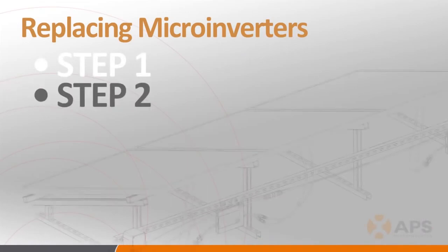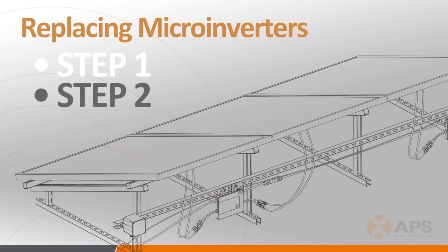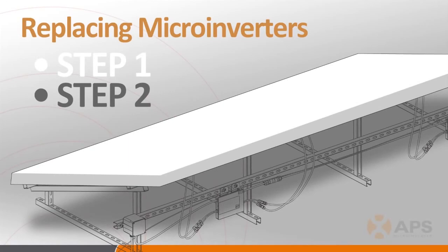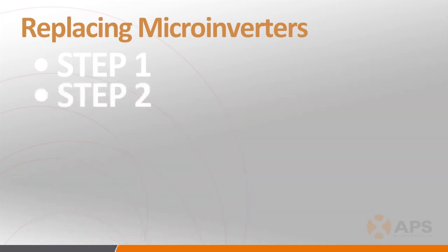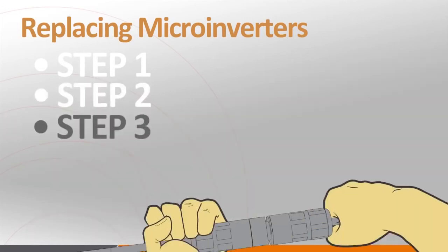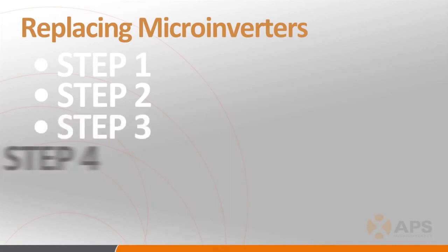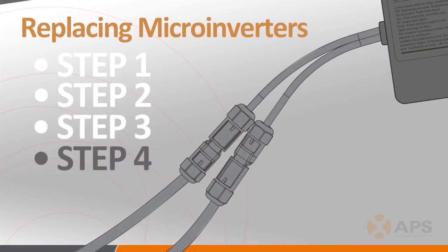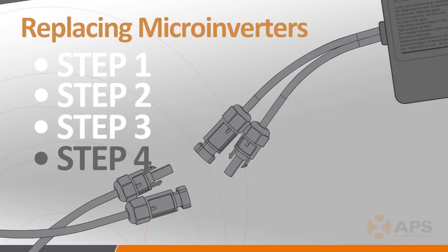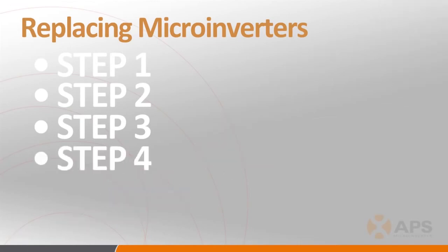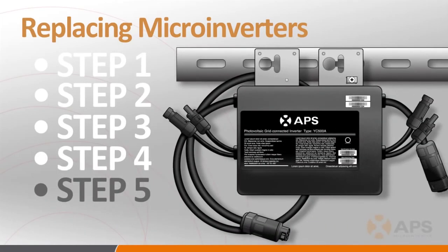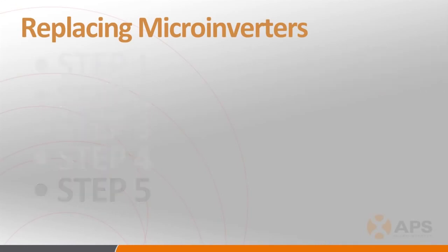With the branch circuit offline, cover the PV modules associated with the inverter to be removed with opaque covers, ensuring the panels are not producing DC power. Next, disconnect the AC connectors to the adjacent inverters. Step 4. Disconnect the DC connectors from the PV modules associated with the inverter. And finally, physically remove the inverter from the rack.